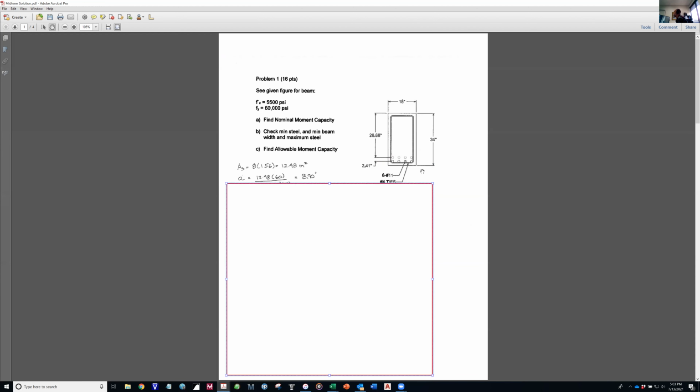From one of those 3 resources, find the published area of steel. You may not calculate the area of steel based on the area of a circle. That does not work and is incorrect, so please do not do that. Always either memorize them or get them from the tables.